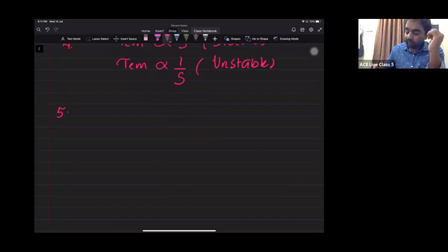See, I have a three-phase induction motor and there is no load on it. When I give a three-phase supply to that induction motor, it will start rotating. Why? As there is no load on the rotor, the motor has to develop only a small amount of torque to compensate that load torque. So it will produce the torque and make the rotor rotate. It is a stable operation.